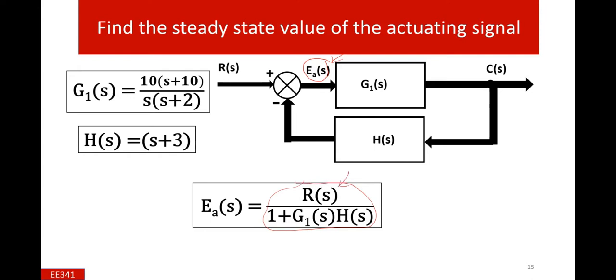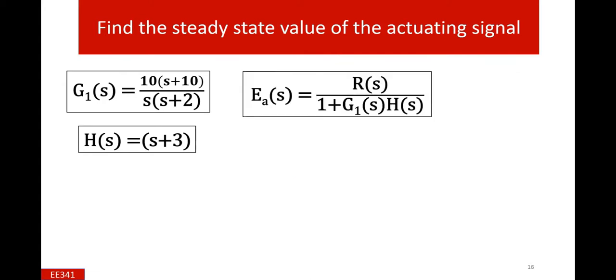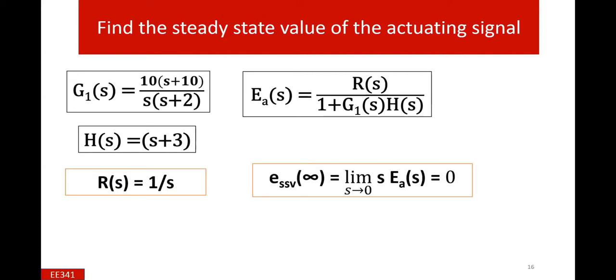And this is the input, and G1 is the forward transfer function, and H is the feedback transfer function. If we use the given values, and we already decided that for this type of system we can use the step input, the Laplace is equal to 1 over s.